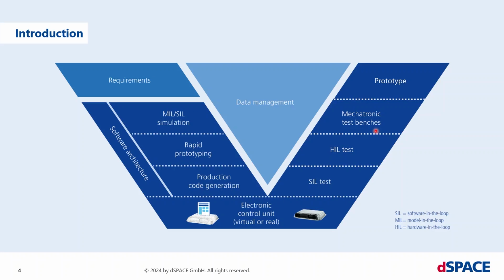When it comes to power level, normally mechatronic test benches are used. The same principle as I explained in the slide before. You have your device under test, for example a machine. You have your load machines, so you have a rotating test bed. And with that mechatronic test bench, you can test your device under test on power level with real currents flowing with full electrical power.